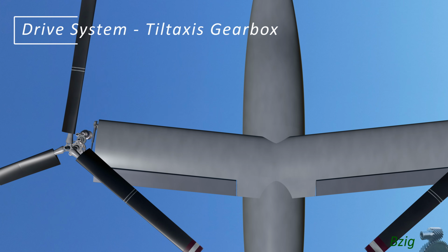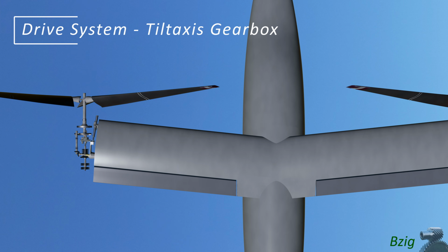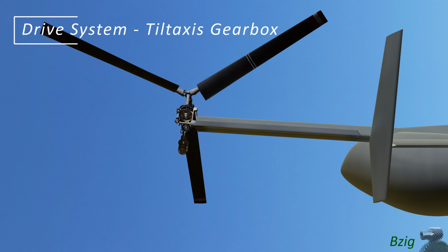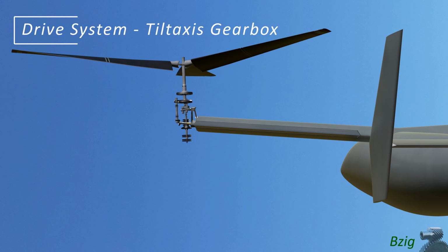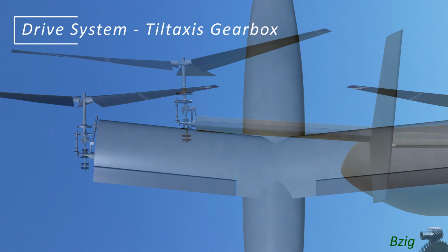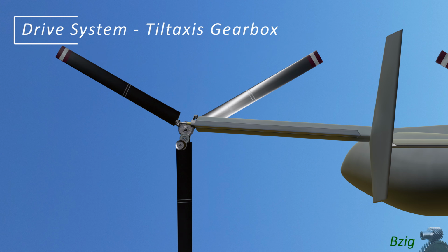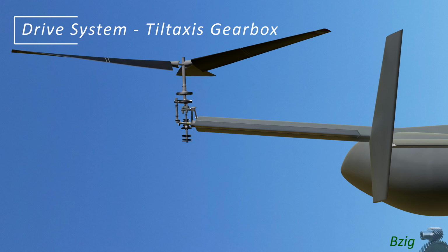This gear pair uses a 96-degree shaft angle to accommodate wing sweep. This results in the thrust axis being aligned with the forward flight direction when in wing-borne flight. But that gear shaft angle also results in the thrust axis being toed out a few degrees in thrust-borne flight. That exact angle is 2.5 degrees, which is the difference between the wing sweep angle of 6 degrees and the dihedral angle of 3.5 degrees. This outward toe-out is a necessity of geometry and isn't intentionally designed in for any aerodynamic reason. In fact, this toe-out causes a slight decrease in hover efficiency because the tip path plane is not parallel to the horizon.